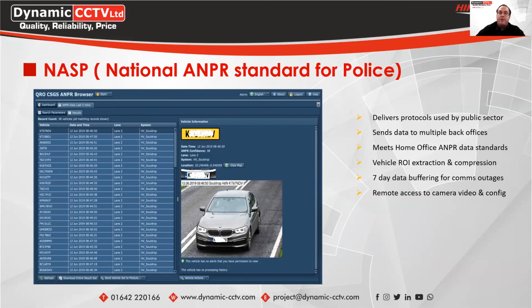So if you do have requirements where the site needs the cameras to meet those standards, then you do have to use the TCM ANPR cameras rather than the standard ANPR cameras or the 7-line cameras. So these are designed for the higher end systems where you do need to meet those requirements for the site.